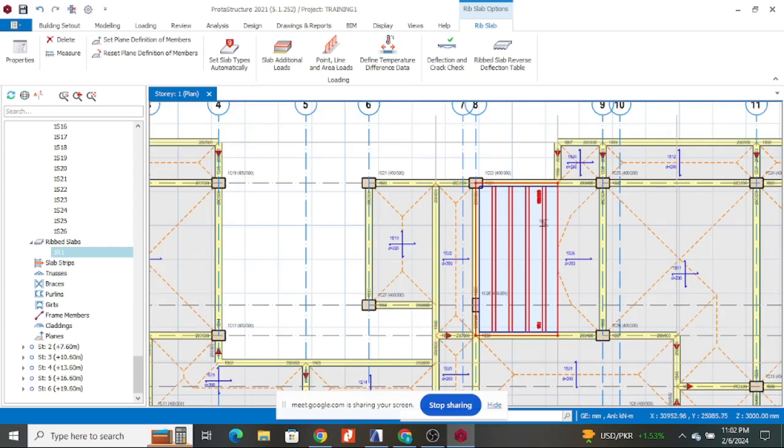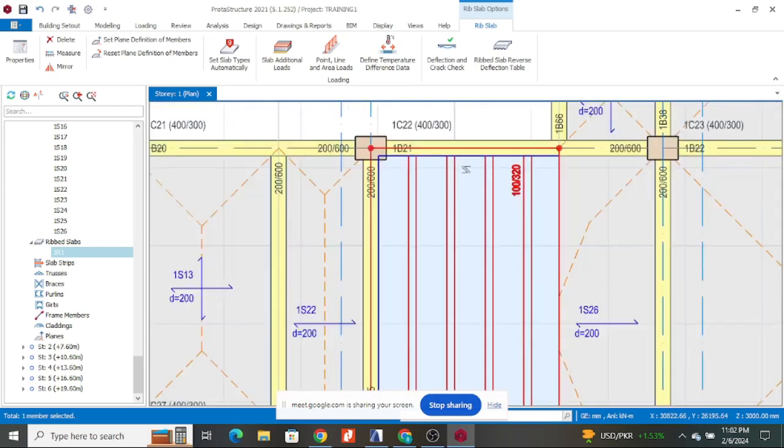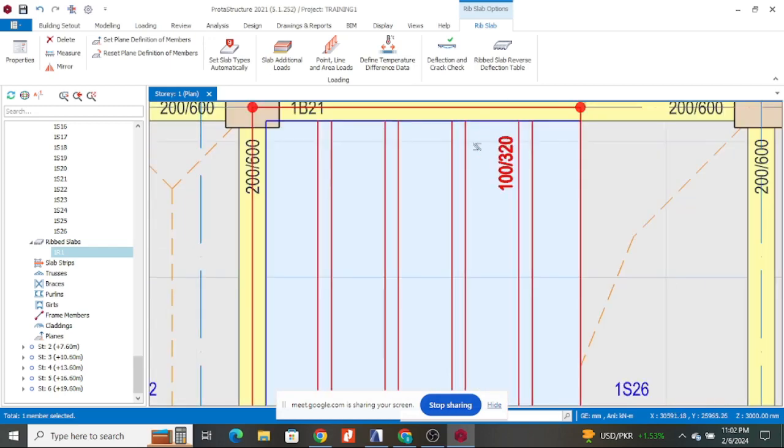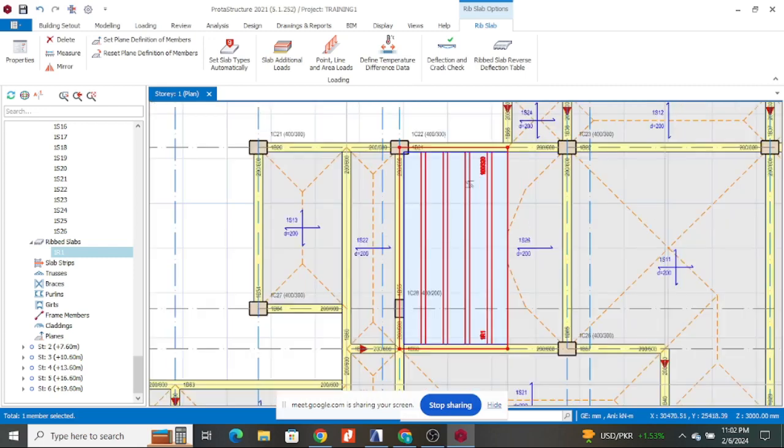And then you also input the dead load. For this, I do not advise somebody who cannot really determine exactly how to do it to go ahead and do it. But I will show you, after we're done modeling, how to model a staircase. For me, I normally do this calculation: I transfer the loading to the dead load of this slab, and then I subject it to variable actions.